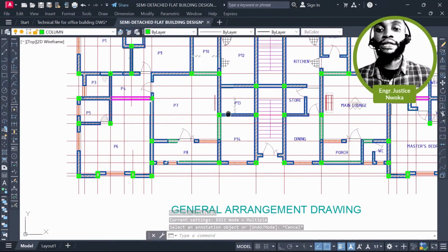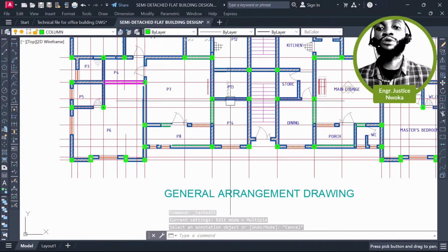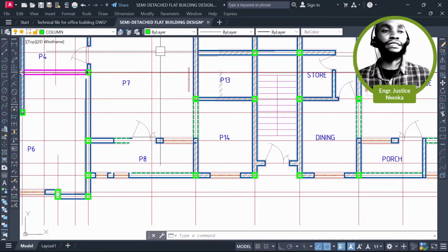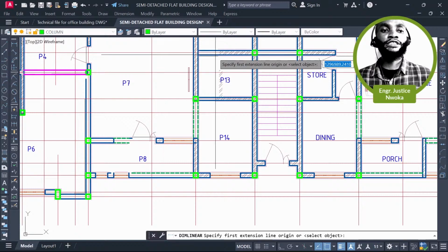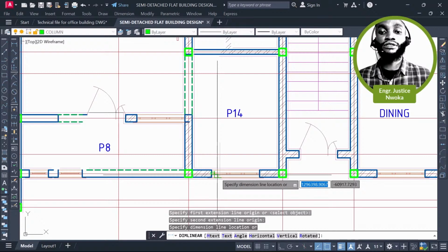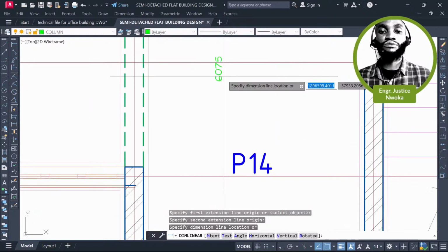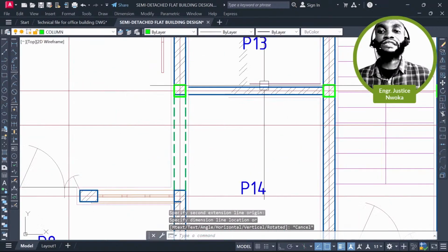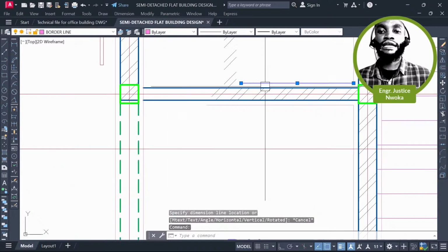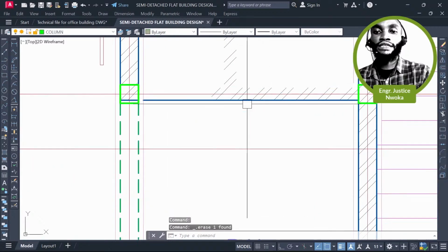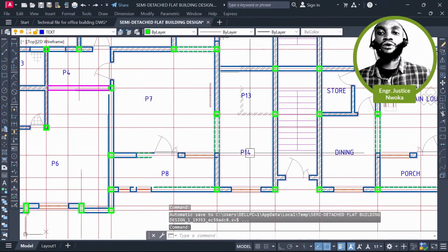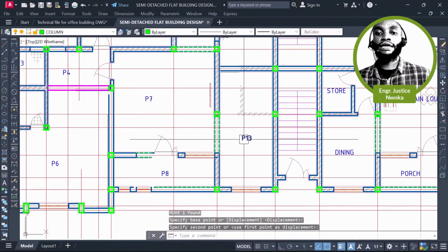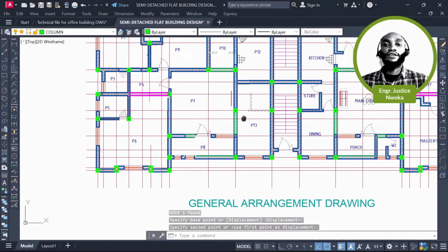So we have 14 panels right now, but I can choose to use this entire place here as one panel, because basically the area of this place here is less than 30. From here to here is around 6.0 multiplied by from here to here, which is the width, that's like 12 or 13. So I can choose to remove this here. Let me just remove this, okay, and remove this here and remove the wall, this beam here, and then call this right now one panel, okay, which is now panel 13. That's fine. Okay, so with this now, we'll move on to the next thing.